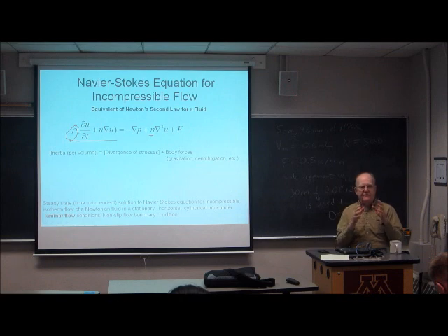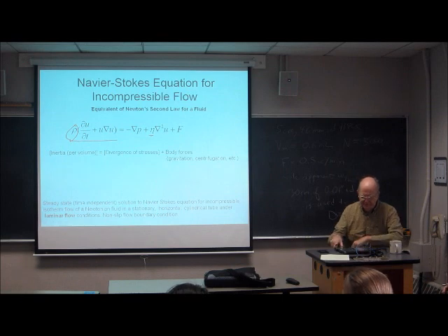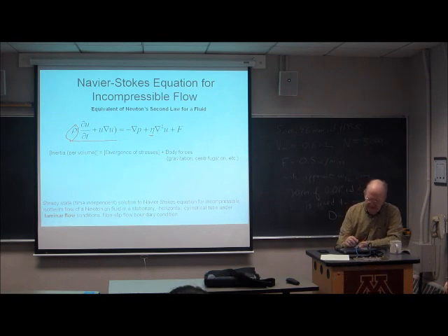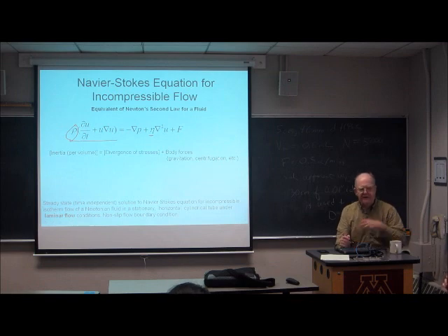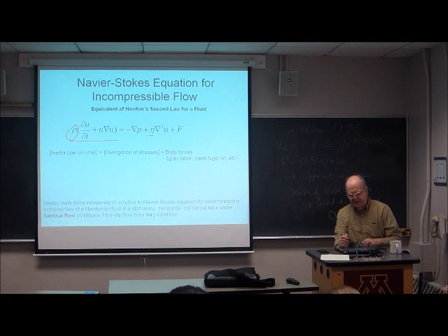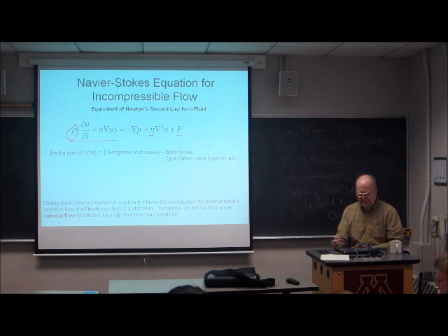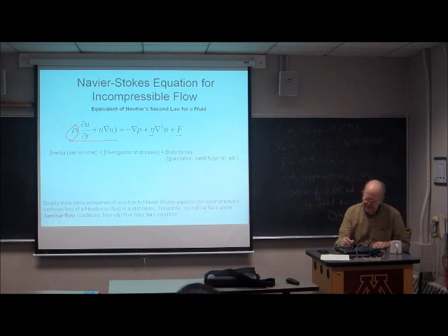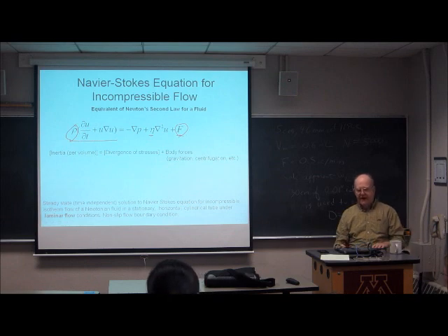The dissipation of the momentum happens through the viscosity. The viscosity is like friction. It's friction among the molecules comprising the liquid. It is the sum of the divergence of the stresses, meaning the pressure, and the viscous drag, plus what we call the body forces. So gravitation, centrifugation, any other force that you can think of to apply to the fluid is gathered together in this capital F.